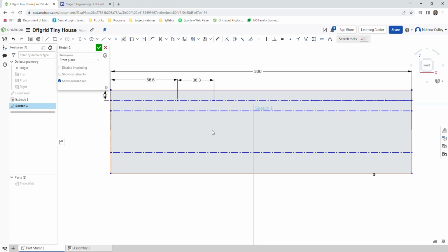Okay, we're going to use our rectangle tool now, so G as the keyboard shortcut. Left click here, coming down, left click again, typing in 3, enter, and escape. And we'll repeat that step over on this end here. So G for corner rectangle, left click once, coming down onto that construction line, left click again, 3, enter, and press escape.